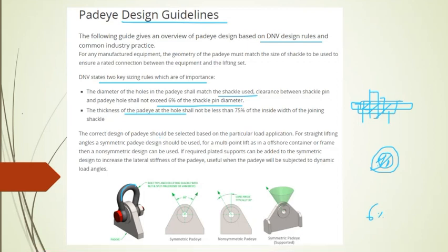For right lifting angles, a symmetric padeye design should be used. For multi-point lifts, as in an offshore container or frame, a non-symmetric design can be used. If required, plated supports can be added to the symmetric design. Plated supports, especially for this main line supports.